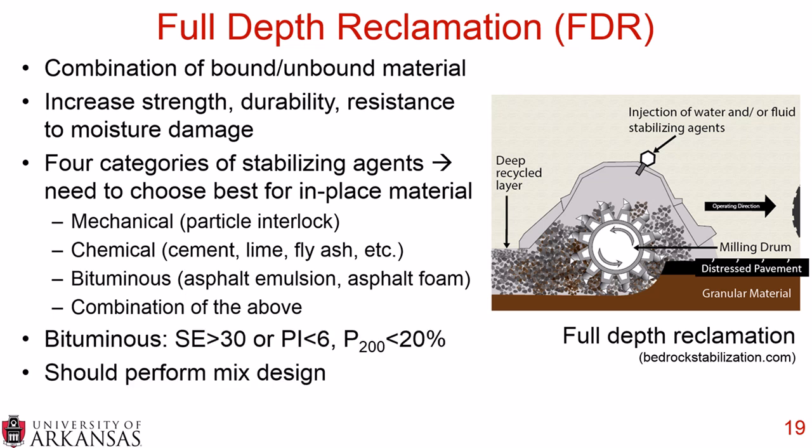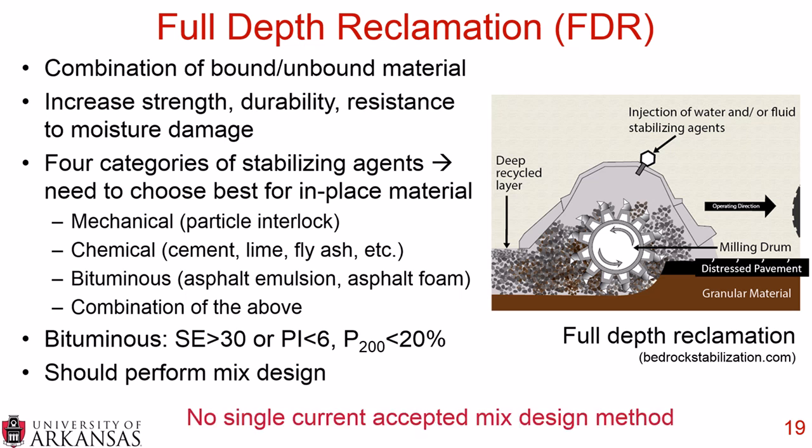Like the base and the subbase, there is a requirement to use the bituminous stabilization. You want that sand equivalency greater than 30, or the plasticity index less than 6, and you want less than 20% P200. You certainly should perform a mix design with FDR because these tend to be a little thicker than the base or the stabilized base layers.